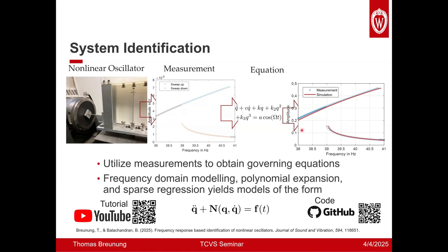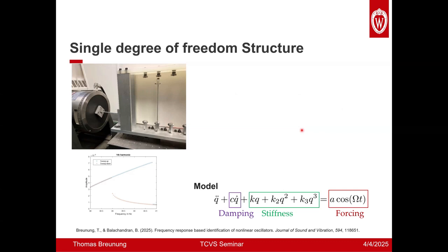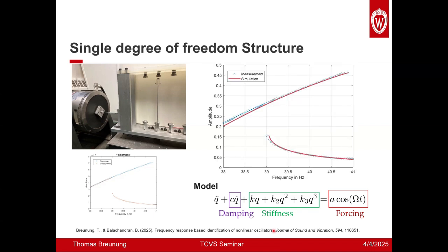And just to show you what comes out for this type of measurement, we have this kind of measurement. And the model is quite simple. It's not some abstract interpolation concept which we cannot really write down. It's just a simple set of equations you can write down on a piece of paper and take next door to your colleague. The terms are also such that we can at least relate physical sources to them. So we have damping, we have nonlinear stiffness and external excitation. And of course, we represent the measurement accurately.